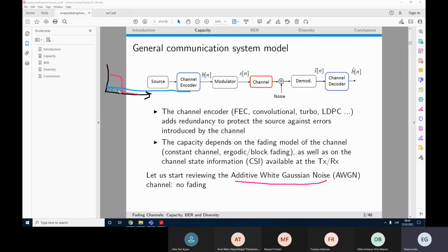So basically, this is the energy of the noise distributed over the whole frequency band from 0 up to infinity. However, our filter limits this, and the energy of the noise is therefore limited only to the amount that got through the passband of our filter. Here we have some symbol frequency F. You have been able to observe this effect in the results, which is when we concluded our practical exercise 2.